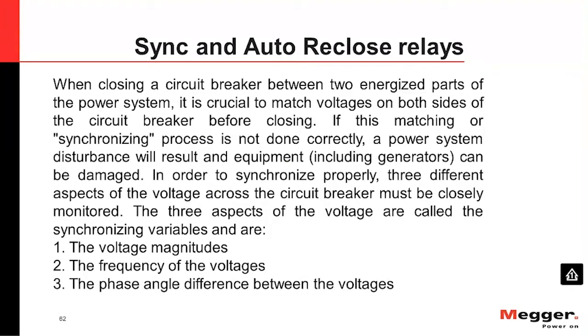Sync relays are the synchronizing relays between 2 different sources, and for these 2 different sources we need to make sure, before closing, to avoid any problem, any unwanted difference in voltage that will create a fault. Things need to be matching: voltage magnitude should be the same, frequency should be the same, and phase angle should be the same, or all of them should be within a limitation depending on the calculation over there.